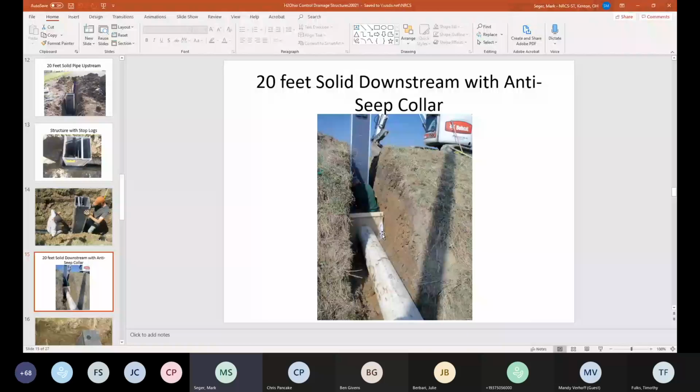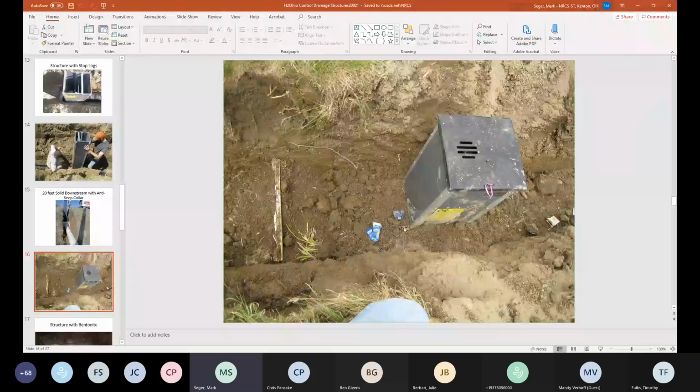Here it is being backfilled around it. You want to backfill on both sides of it. When you're backfilling around the structure itself, you need to make sure that they're not using mechanical means to compact around it, that they're hand compacting. Because with these boxes, if you put too much compaction on one side, you could kind of warp these boxes. So you have to be careful on the backfill of these things that you don't distort the structures themselves.